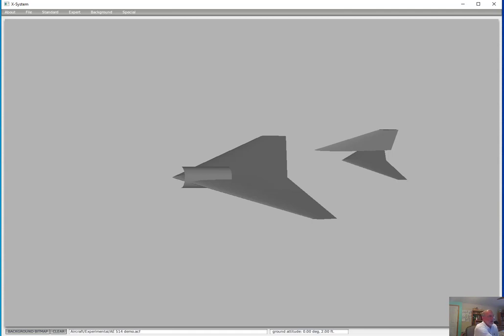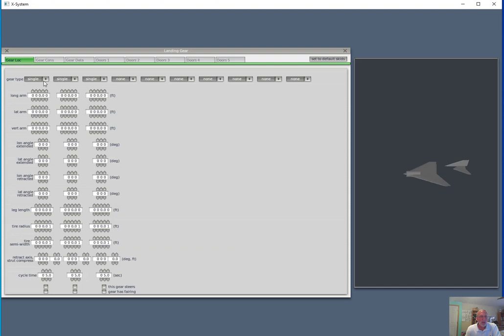Alright, so flip over to the next page that talks about the landing gear. The landing gear is kind of tedious because you have to tell it where each gear is, where the location is, how long the landing gear is, what the size of the tire is. But we'll click through that pretty quickly. So go to standard, go down to landing gear, and we're going to create 2 lateral landing gear.